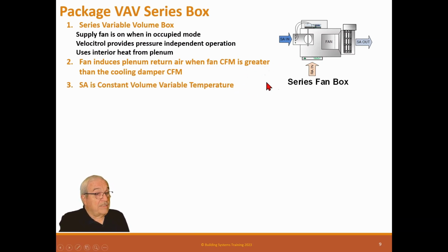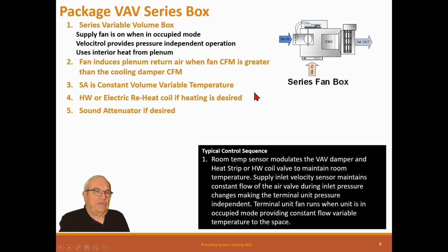Well, that's exactly opposite of what the VAV is, right? Remember, VAV is constant temperature, variable flow. Well, this box turns that into supply air is constant volume, variable temperature. Hot water electric reheat if you need it. Sound attenuator if desired. The sequence is the same.